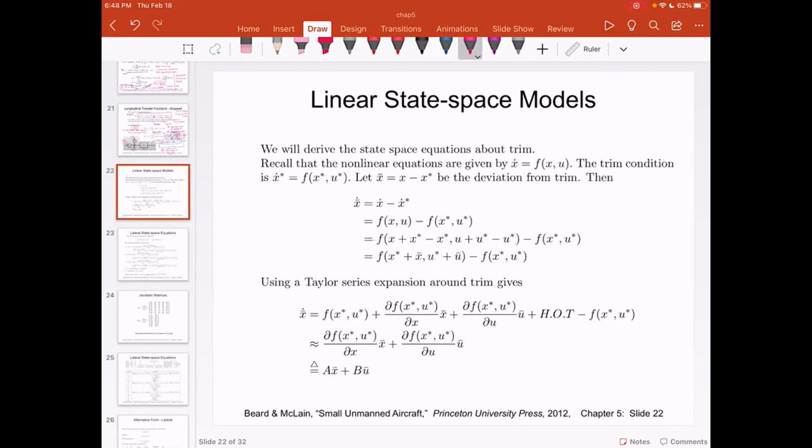Yes. Now, what we are trying to do is come up with some sort of algorithm or some sort of control law that would change the elevon and the thrust input. It will adjust the elevon and thrust input based on the roll, pitch, and yaw, based on the wind condition, so that the aircraft self stabilizes.